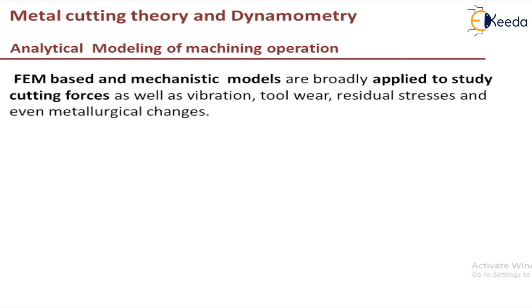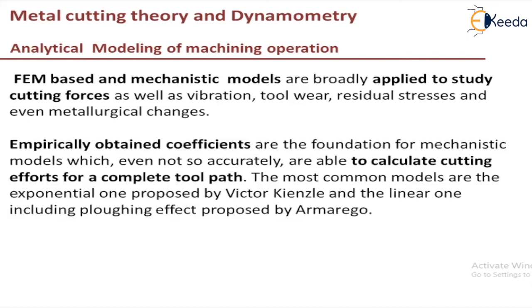So both FEM based and analytical modeling, that is mechanistic models, are applied to study the cutting forces as well as vibration, tool wear, residual stresses, and even metallurgical changes. What you do in this analytical modeling is, as I said earlier, you develop a mathematical equation based on the physics of the cutting operation, and you obtain the coefficients. These are the foundation of mechanistic models. Even if not so accurately, they are able to calculate the cutting efforts for a complete tool path.